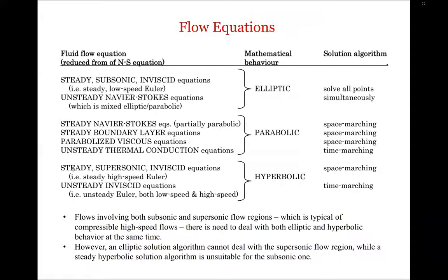Steady supersonic inviscid equations and unsteady inviscid equations are hyperbolic, and the steady supersonic inviscid are space marching while unsteady are time marching.